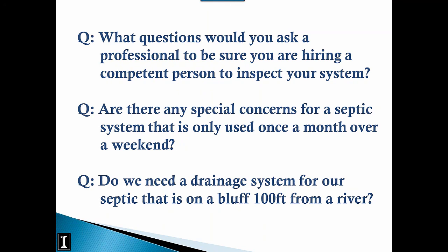The one thing I would definitely say when they come to inspect your system is to make sure they open every manhole in your whole system. Open up, whether it be 2 or 3 manholes in your septic tank. If there's a D-box, they open that up to inspect each and every one to make sure all the components inside are functioning as corrected.